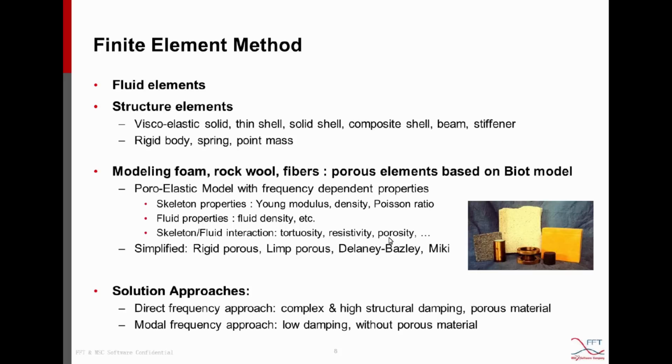Then in Actran, we implement some simplified models, like the rigid porous model that assumes perfect rigidity of the skeleton, so the skeleton cannot be compressed, or lumped porous, which assumes a very soft skeleton.